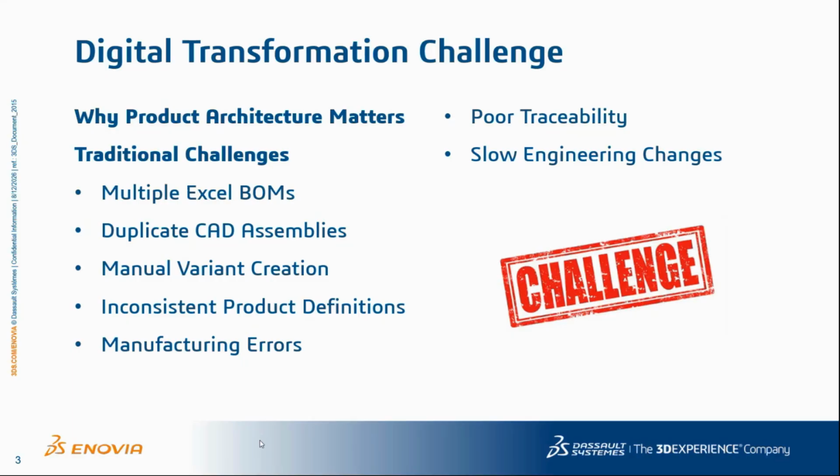Your product has more than one version, where everything remains the same but only one or two components differ. In that case, we call it a variant. Maybe you take a product where the part numbers, the detail parts, everything is the same, but only the color or the material of the product gets changed. In that case, it is not mandatory that we recreate the complete 3D models in SolidWorks or any other 3D CAD which you have.